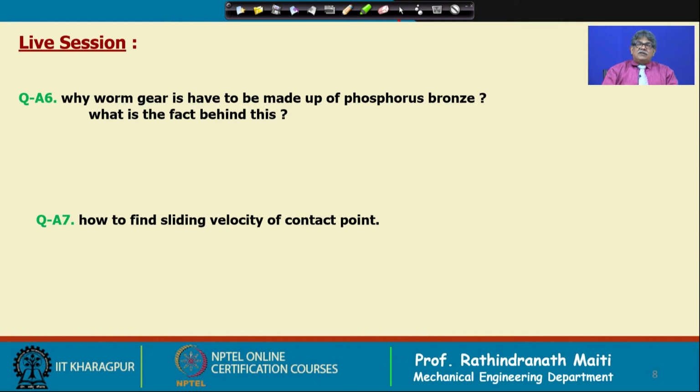But if you divide by the cos cube of the 90 degree minus pitch, that will be a good number. So there you will find these teeth have a high form factor, and can take high load as well.